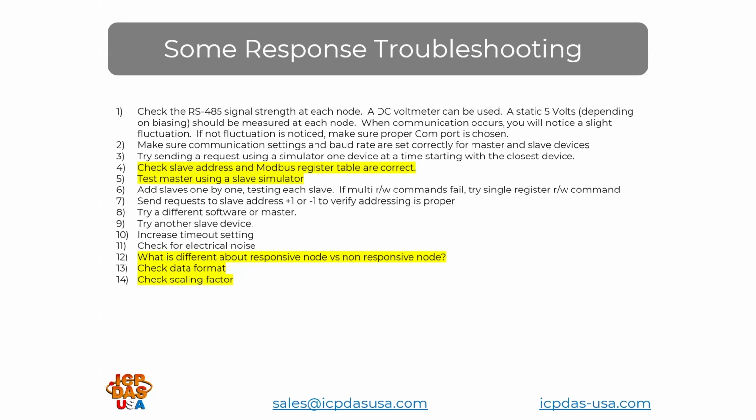very clear. Sometimes we like to start off at registers like 40,001, 30,001 for our register tables, but sometimes they come up with these weird numbers that are in the middle of the whole range, and it just makes it hard to tell whether it's base 1 or base 0, and it is not very clear, so sometimes you have to test. That's why I always like to pick one register with a known value to try to test with first.